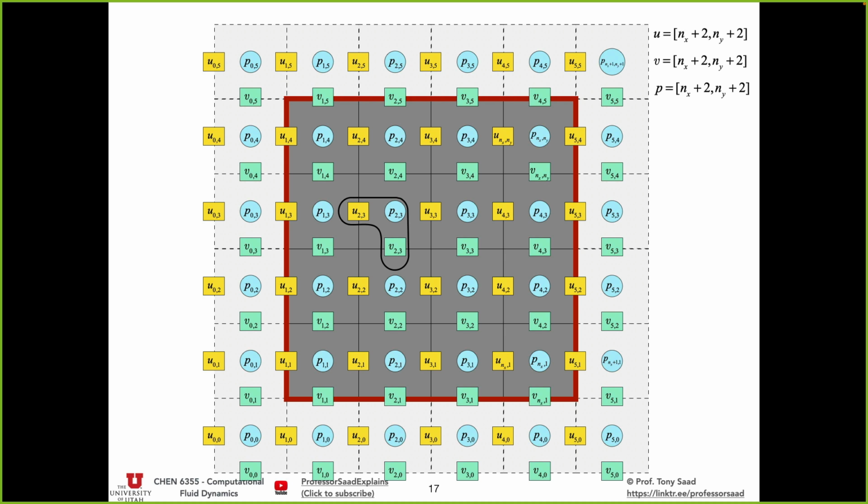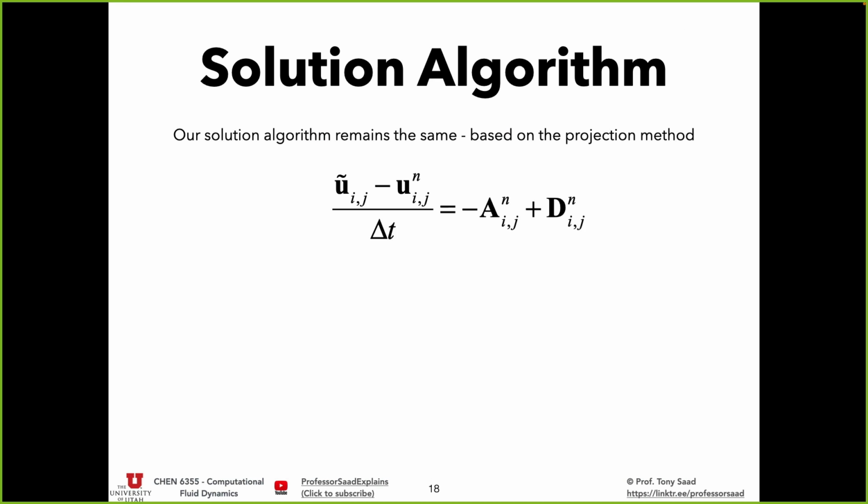Top wall, you say, well, okay, my v is 0 everywhere, so I can set these points to 0. But my u, I'm talking about the top wall, it's a sliding wall. I don't have a u variable living on this wall. So I have to set the ghost cells. Okay, so I use the average of these to reproduce u wall. Okay, that's the reasoning I'm trying to convey to you.